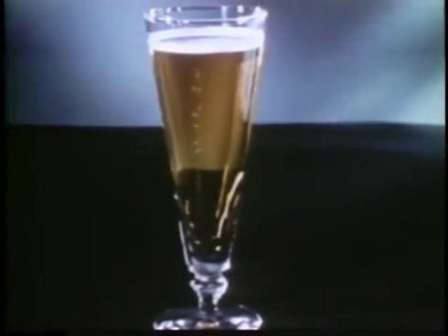Actually, it is possible to make new bubbles in a liquid, but you won't do it by normal boiling. Water carefully cleared of all bubbles can withstand a tensile stress of over 5,000 pounds per square inch. Water molecules attract each other so strongly that it takes at least that much tension to pull them apart. When a liquid contains a large amount of dissolved gas, such as carbon dioxide, it comes out as bubbles. It comes out wherever there are nucleation sites that provide a surface across which the molecules can pass into vapor spaces.